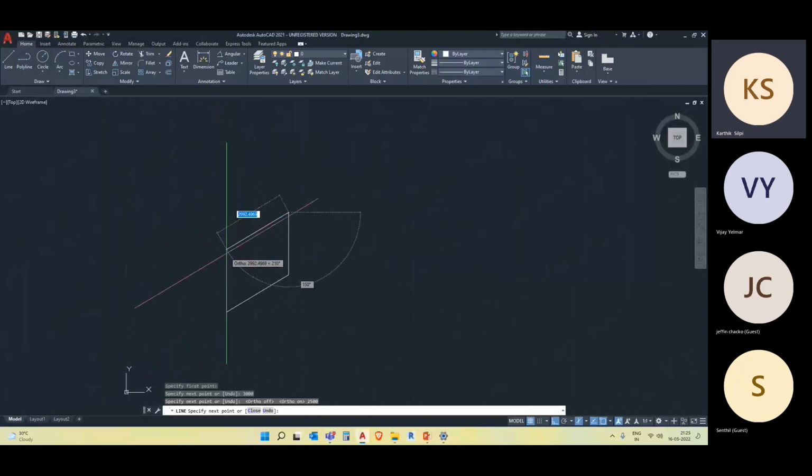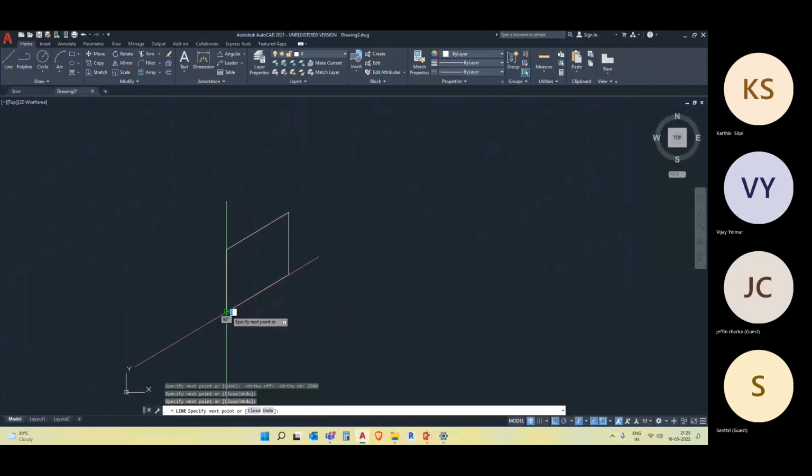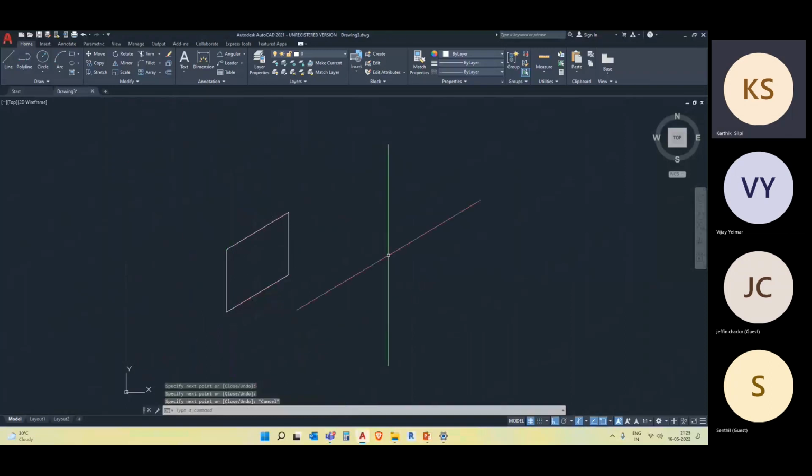Now, if you want to draw a line which is equal to this line, you can take a reference from the bottom line. How? Just scroll down gently, and you have to touch this bottom line like this. As soon as you go up, you can see there is a reference line. If you click on that particular line, it will end. You can see that line ended over there. And if you want to connect, then again, try to drag like this. It'll help us to find where our dimension is exactly. Now if you want to join everything, press J, enter.